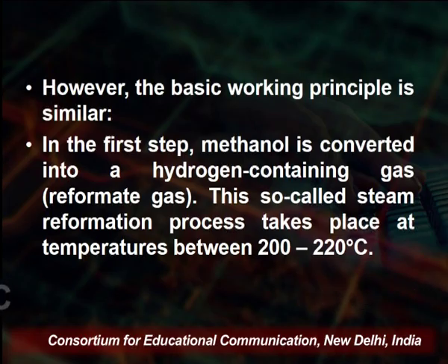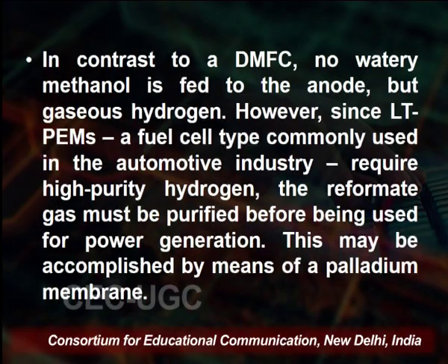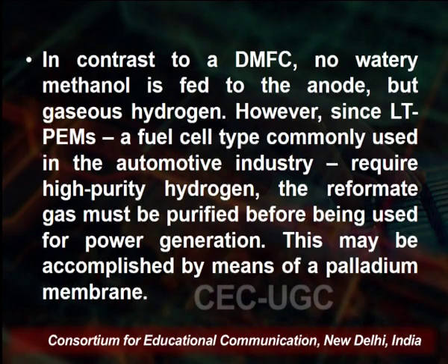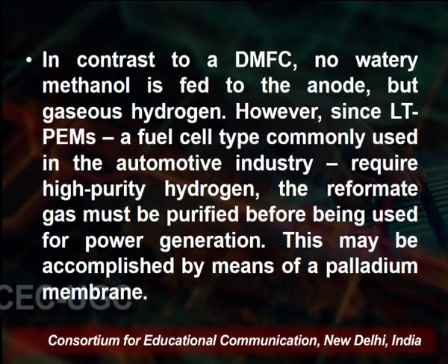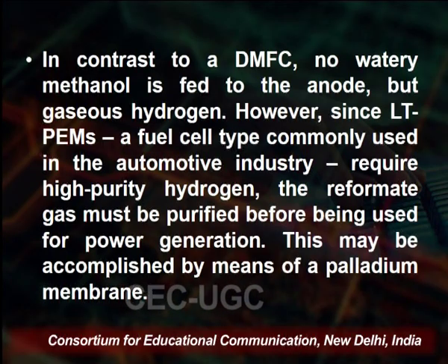First step, methanol is converted into a hydrogen containing gas, that is reformate gas. This so-called steam reformation process takes place at a temperature of 200 degrees centigrade. In contrast to DMFC, no watery methanol is led to the anode, but gaseous hydrogen is used.